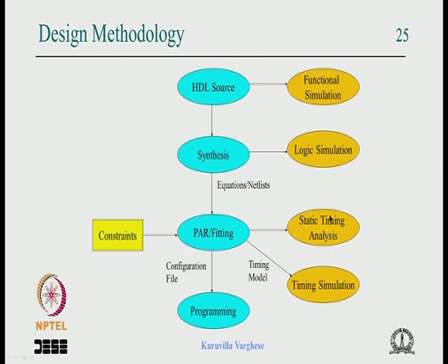So it will assume that all the registers are working all the time, upon every clock edge. It will overestimate the critical path delay and there could be errors. So this has to be told to the timing analysis tool, then it will be very fast.